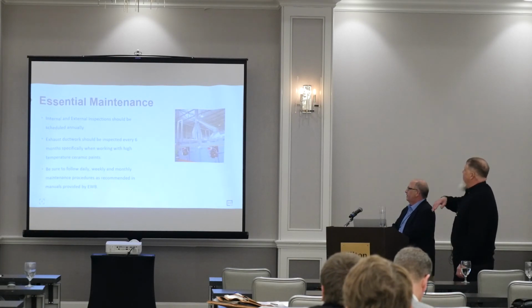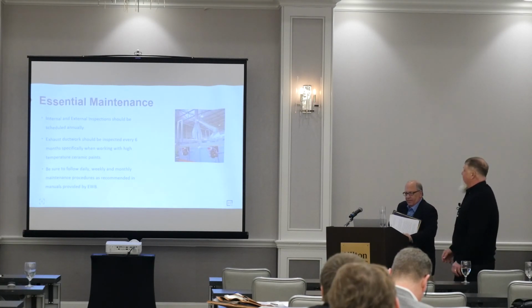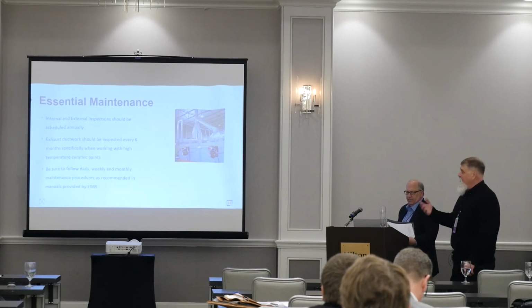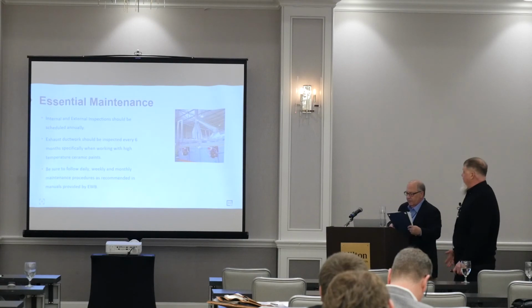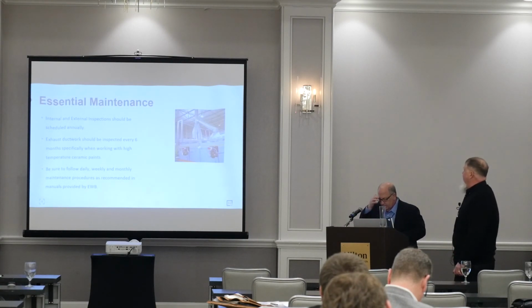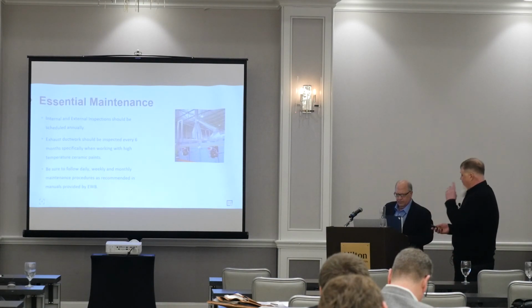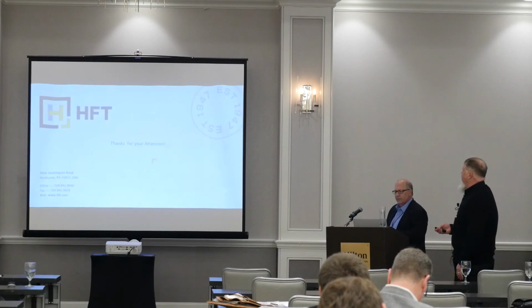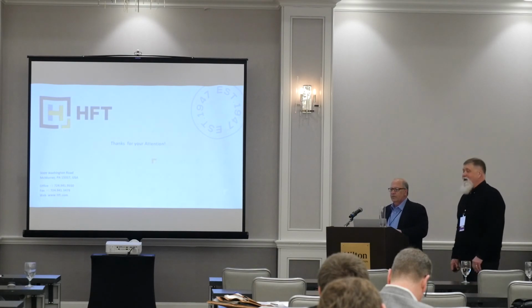The ductwork I mentioned earlier, as much as you can, if you've got inspection ports or doors in your exhaust ductwork, keep an eye on that, because if you get a lot of the volatiles built up on that ductwork, it can and will catch fire under certain conditions. So keep an eye on that, and of course, just do the obvious: follow the procedures in the manuals as you have them, and that's basically all I have.